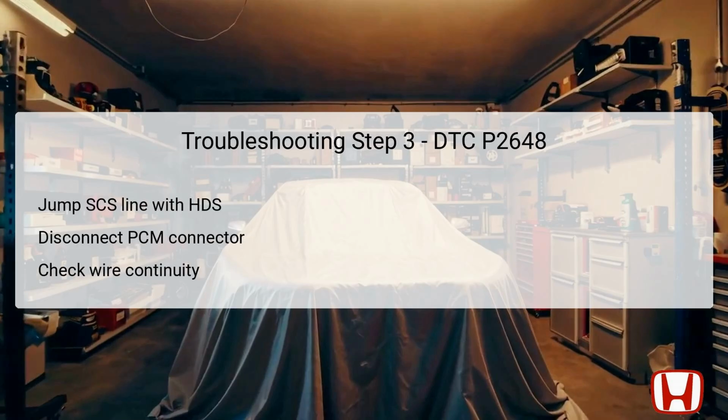The third step in troubleshooting DTC P2648 requires jumping the SCS line with the HDS, which allows for proper diagnostic protocol engagement. Following this, disconnect the PCM connector C51P, as this step ensures that testing does not encounter any interference from the PCM during continuity checks.